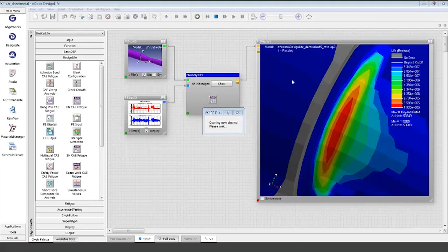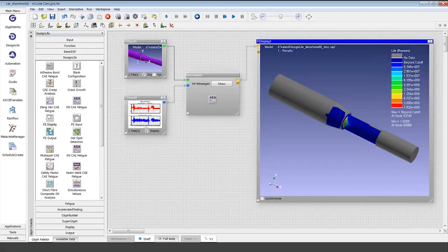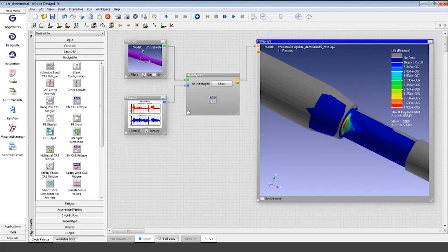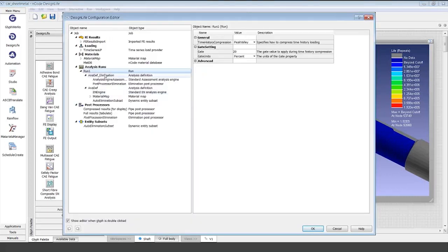So we run this now. It's going to work through the same hotspots as before. Let's look at the full model here again, like this. So it's going to work through the full model again. The difference is that now it's not working with the full time history. It's being smart about what data points it needs to actually superimpose stresses from in the time domain, such that it doesn't waste its time looking at combined stresses if they're not changing, or if those combined stresses are quite small.